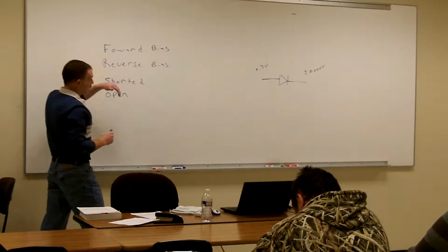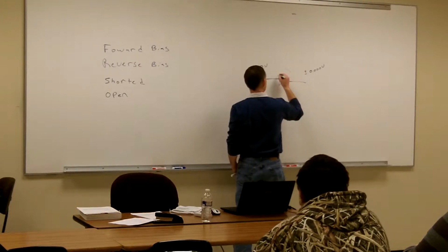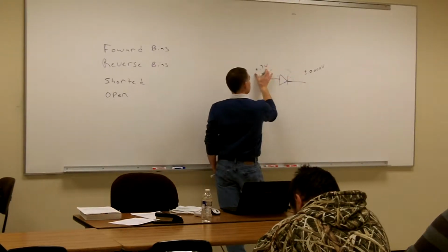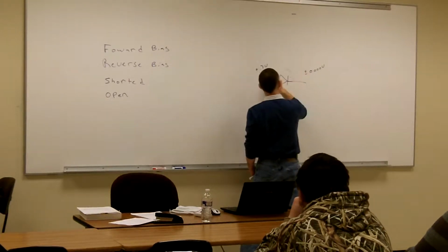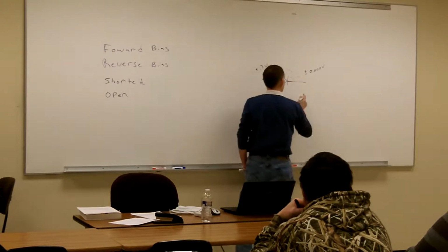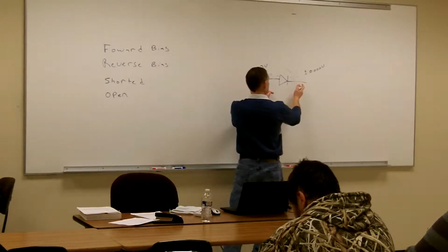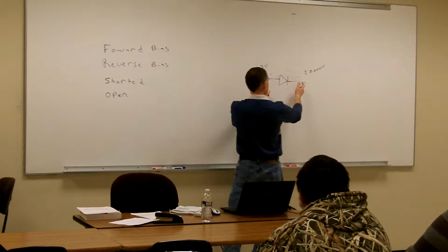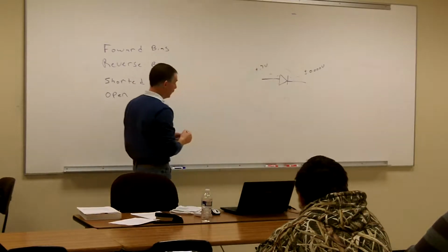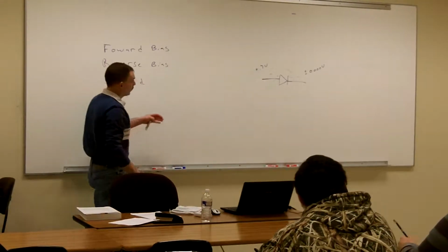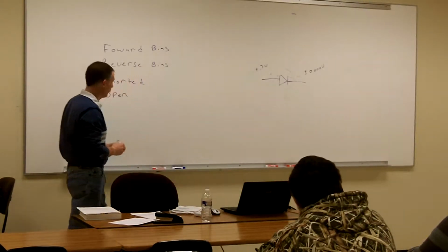It's going to be in a forward bias because if we circle our active component and put in our polarities, my anode side is more positive than my cathode. My cathode side is going to be, relative to my anode side, more negative. So my polarities are matching on each side of that. It's going to be forward biasing. And if I were to take a voltmeter across there and measure it, I'd measure 0.7 volts going across there. So it's a forward bias, it's turned on, and it's going to drop to 0.7 volts.